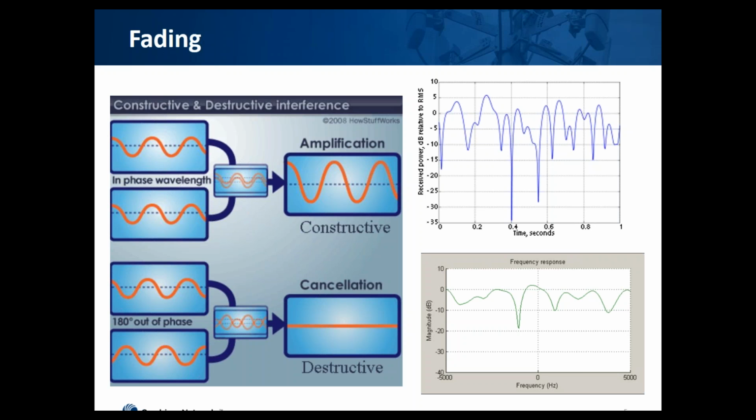You probably have experienced fading if you listen to the radio while driving. It can happen that you stop in one location and you hear only static noise on the radio. But if you move just a little, you now hear the music clearly. This happens because the first location is where the signals add up destructively. The combined signal is so small, you only hear the static noise in the background. But moving just a little shifts the phase of the signals, and now they add up constructively.